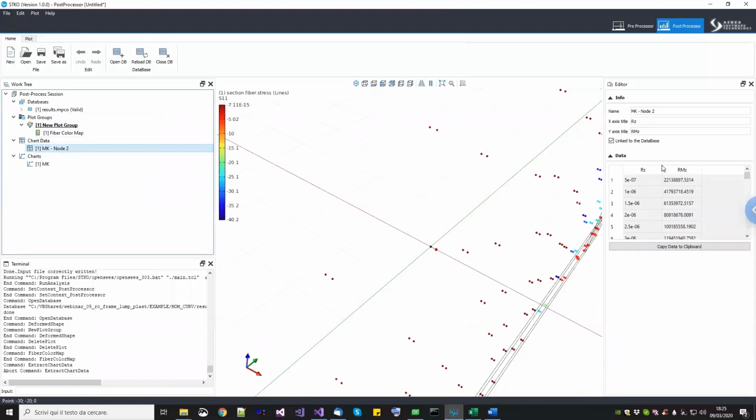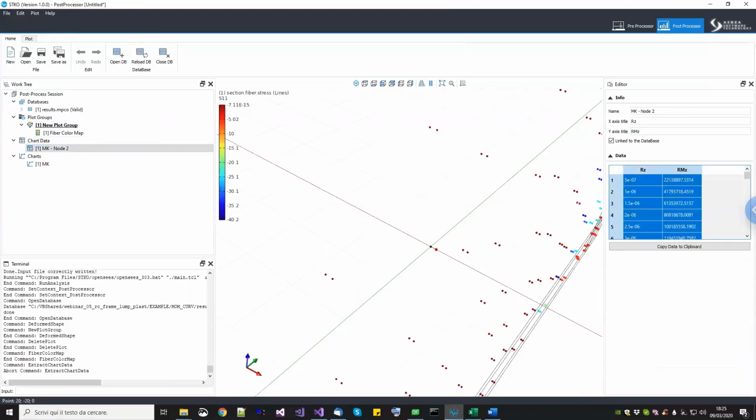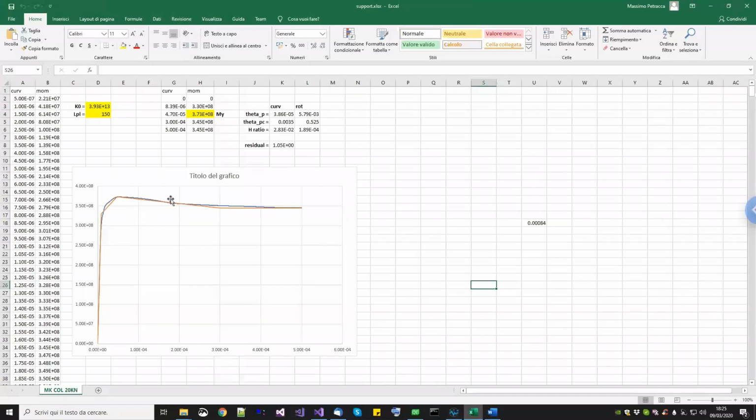Now, of course, you can go here, copy paste these values. You can go to Excel. I already did it, so you can find this file there. Now, what we want to do actually is to use this moment curvature. As I said, this one is the moment curvature response of that section for a level of axial load equal to 20 kilonewtons. Now, basically, what I did is simply a fitting of 4 points used for the Medina-Krawinkler rotational spring. So we had the same initial stiffness, then I took a point here, the peak point at this point, and then the residual strength, okay?